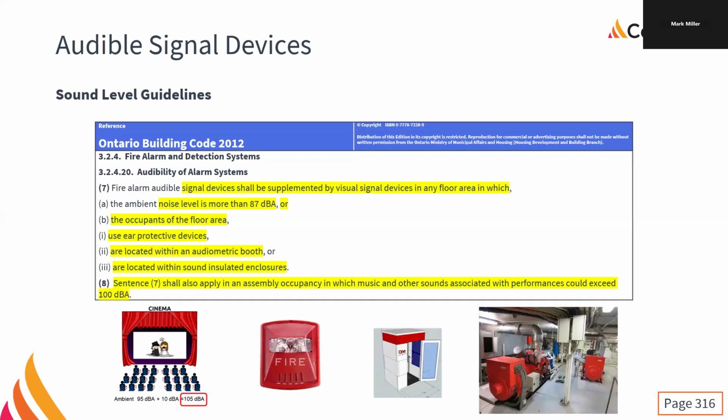Totally makes sense. In the shopping malls now, as every unit gets renovated and a new tenant comes in, we put in a music shutdown relay so that the thumping music inside the store, to keep all the old people like me out of the store, turns off when the fire alarm activates.